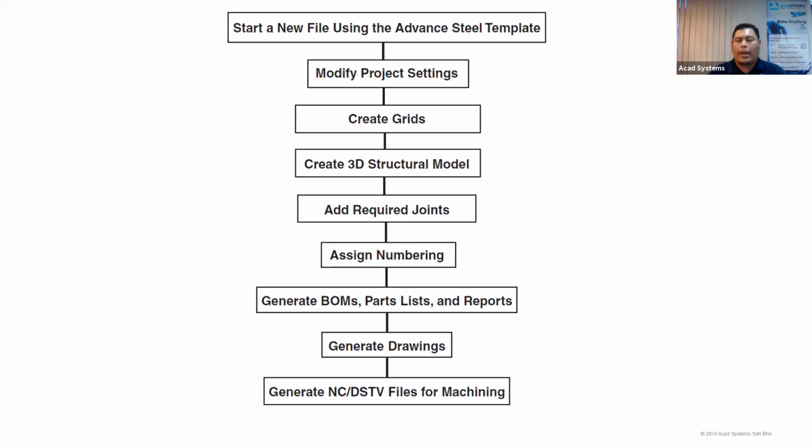So if you are working with a Japanese code, Eurocode, BS code, AISC and so on, Advanced Steel has acquired all of these joint code standards. And you should not be worried about those codes, because most of the common connections, especially on the plates, bolts, nuts and anchors, are far more accurate and better than what you can do with Revit.